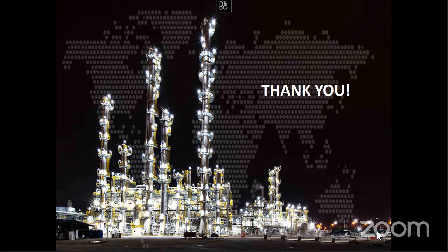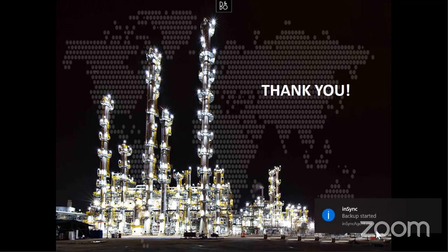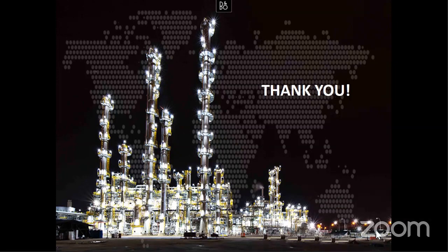But we've done things to work around that. We have the highest power levels allowed by the FCC, so we can actually do more than what we say, because we want to survive in these nasty industrial environments. And we also have the ability, which not a lot of people do, to change the channel. Even though we're at 2.4 gigahertz, which is where most people are, we can choose one of about 14 different channels. So you can pick an area that's a little cleaner and avoid interference. We do a lot to make sure we don't have interference, and so far it's been pretty solid. But if you know you have a really noisy area, you might want to do some sniffing and take a look at what interference might be out there.